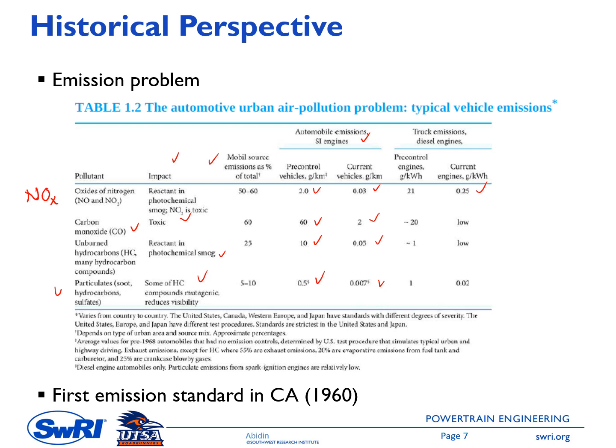And this is the number for CO. A spark ignited engine usually produces about 2 gram CO per kilometer. In a diesel engine, because it usually operates with a lean mixture, I think you remember in Thermo 2 what the lean and rich mixture mean. A lean mixture means we have more air in the combustion.